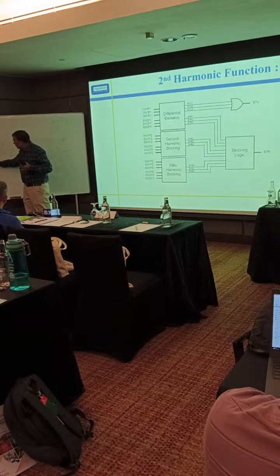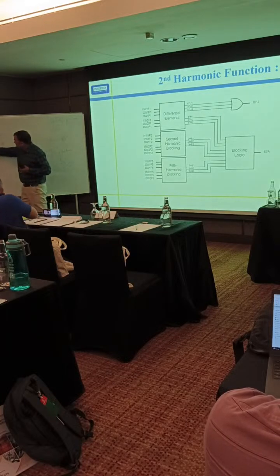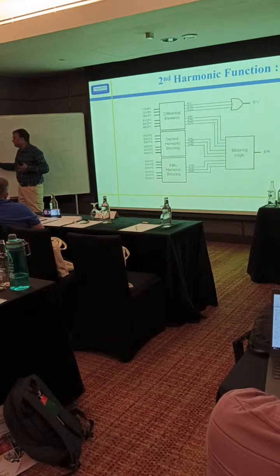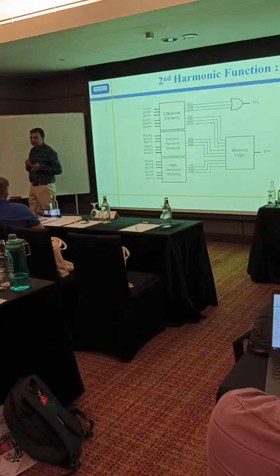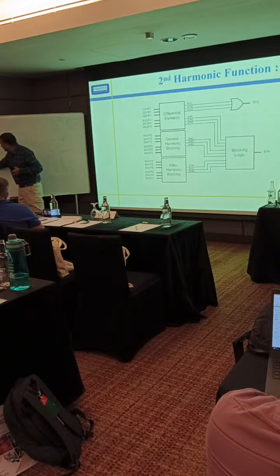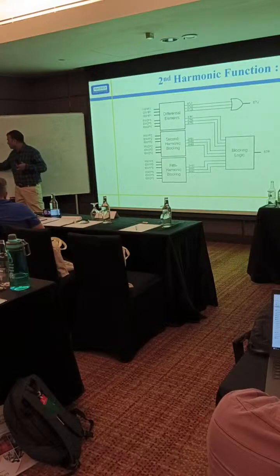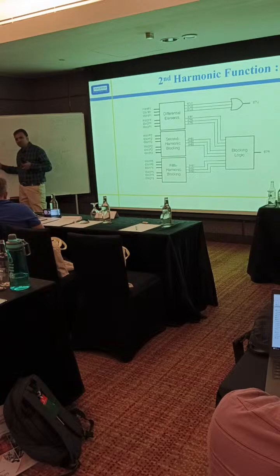But in any case, if a differential current is there, if we test through the state simulation, and it is more than this, then it will not consider this bias setting. It will immediately give the tripping command. So just before this point, if we check, it will block. If we consider just this point and this point, it will block. But as soon as the differential current reaches this point, it will immediately trip.